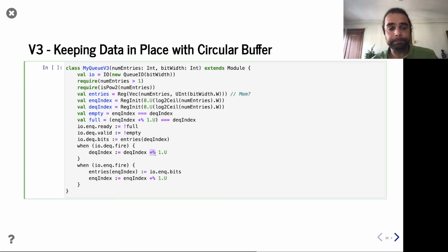If you remember from a few lectures ago, when building our counter, we asked whether we could be clever and recognize that the thing we're counting to is a power of 2, and perhaps not have a comparator for finding that max value and just use natural wrapping around. If it wasn't a power of 2, we'd do this optimization manually ourselves, and we observed how the Chisel standard library counter automatically considered both possibilities.